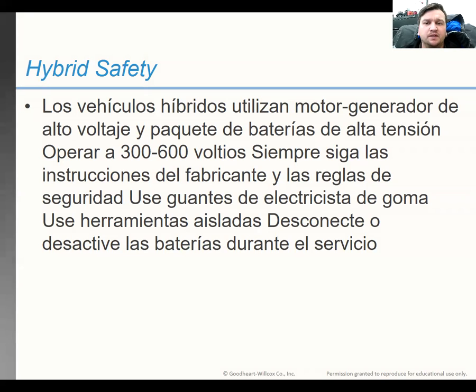Right, hybrid vehicles, they use very high voltage motor generators and batteries. They can operate from 300 to 600 volts. They're very high voltage. You'll always want to make sure to follow manufacturer's safety rules. Wear rubberized electrical gloves. Use insulated tools. That way the metal tools aren't going to cause any type of short circuits. They're insulated to prevent that, as well as disconnect and disable batteries during service. Follow your manufacturer's service manual to guide you on how to do that.